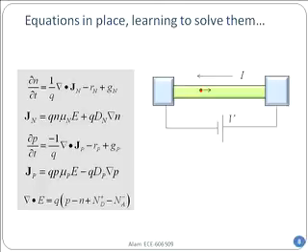How so? Isn't there a recombination rate present there, R sub n or R sub p? Well, yes, but remember, in Shockley-Read recombination, I will replace that term as np minus ni squared divided by the big denominator. So that term inside it actually only has n and p. So I can forget about that.